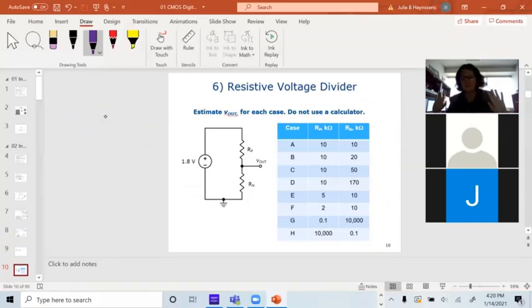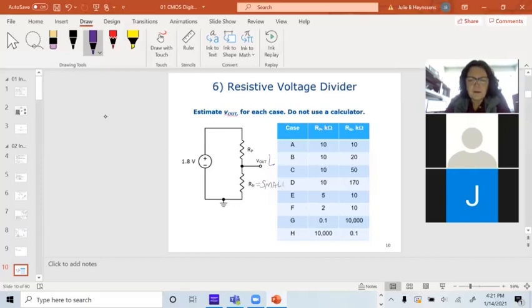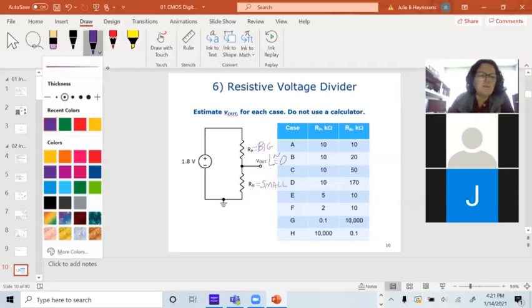So here's the big idea. And this thing again, huh? I've seen this in 280 a lot. This is a voltage divider. So what I want when the output is low is I want this resistance to be as small as it possibly can, and I want this resistance to be as big as it possibly can. And then my voltage will pull closer to 0.